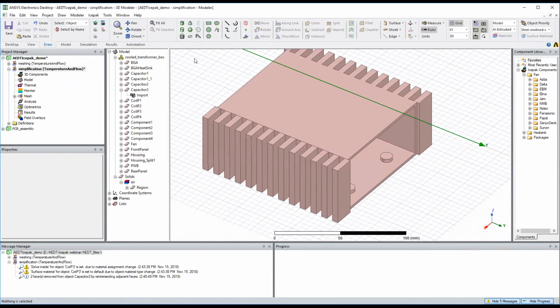One of the other options is an align faces option, like a pull command in SpaceClaim. It'll take two objects, if there's a gap between the faces that are parallel to each other, and it'll pull one face towards the other depending upon what order you select the faces in. So those are some common ones.